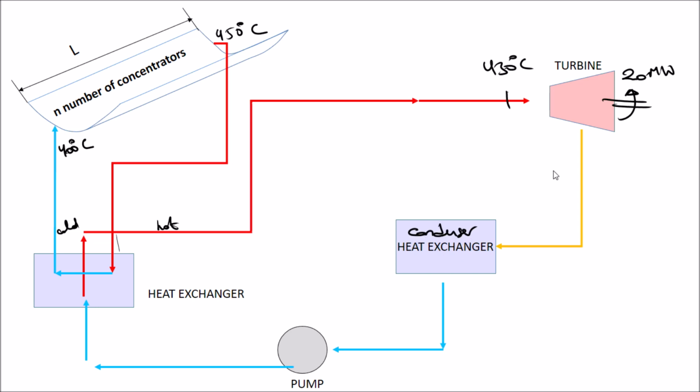The outlet of the turbine is sent to the condenser, and there it gives off its heat again. This is the requirement of the pump, because the turbine outlet is two-phase and the pump cannot handle two-phase fluids. Or the second law of thermodynamics requires that if you have some heat input, you should also have heat output.